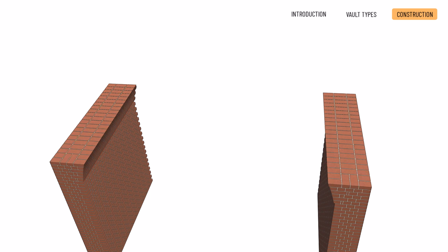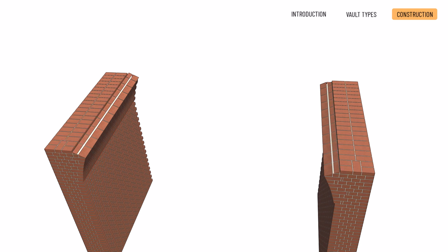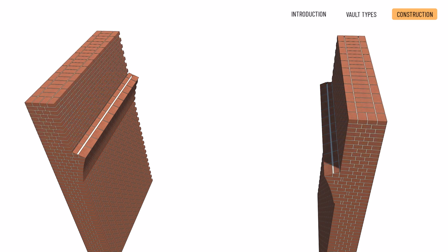2. To allow the joining of the arch at an angle, the bricks need to be increasingly cantilevered. A brick support with a sloping starting plane is formed from a straight plane with quarter and half bats. This creates a sloped starting plane with carved elements, which is typically 1 brick wide. This is the impost width. 3. Above the impost, the masonry continues upwards with vertical planes, and from the spring line you can start the masonry of the vault on 2 sides. The part between the two is usually reinforced with masonry infill.